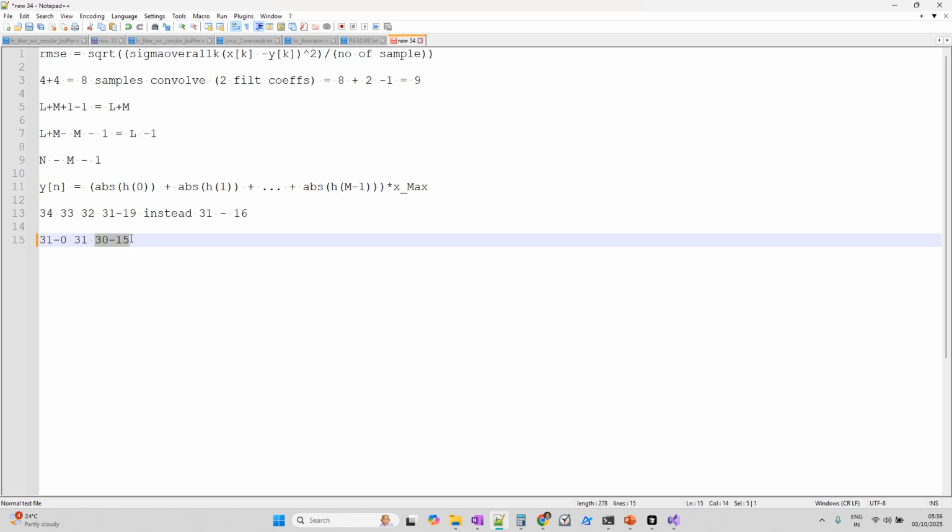16 bits will come. So for this, what you have to do, this entire thing we have to shift right by 15. Then we will get bits 30 to 15 in the lower part, and then when you convert into short, these bits will be taken. Okay, so that's the idea. 30 to 15 you will take, so these will be 16 bits.